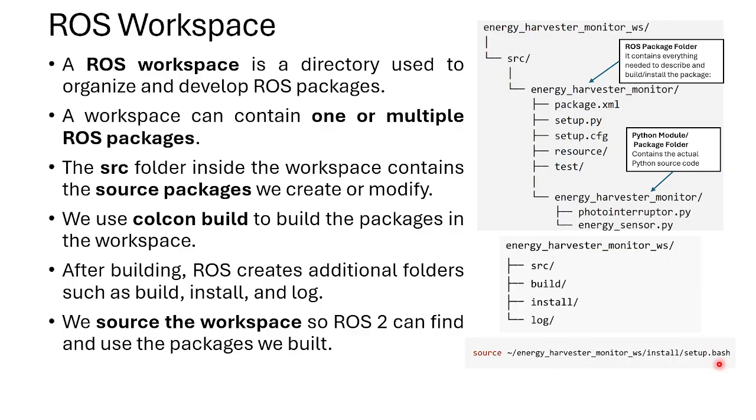It's a very fundamental stage, and we do this in a terminal. So we do all the steps to create the workspace directory, and after that we create the source folder, which will have the core stuff that is required for the package. Then in parallel, we will also create these other folders like build, install, and log, which are created by simply executing colcon build.